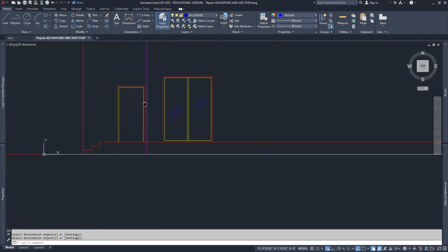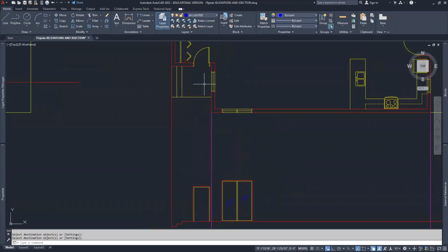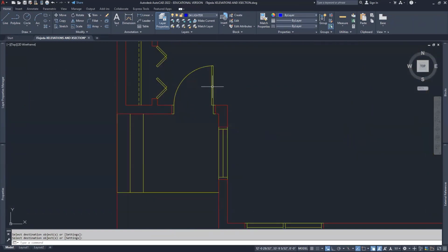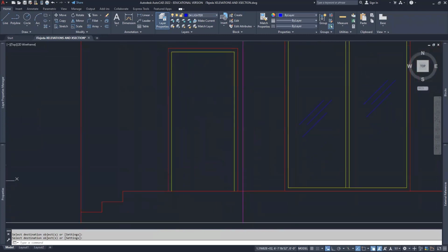And then for doors, in elevation, we draw 2 lines. And let me show you. I'm looking at my door. I'm going to draw 2 lines, and the 2 lines end up meeting at the pivot point. So this is the pivot point. It happens to be right here on the right-hand side. And I've done that on purpose. And I'm thinking maybe it could flip in the other direction, but for now, I'll leave it alone. Here's what I need to do on my elevations. I'm going to come in here. I'm going to draw a line. So I'll type L, enter.